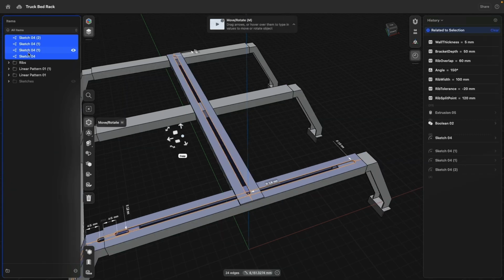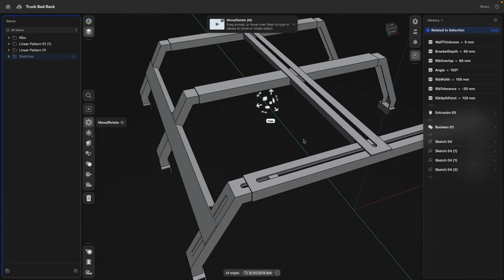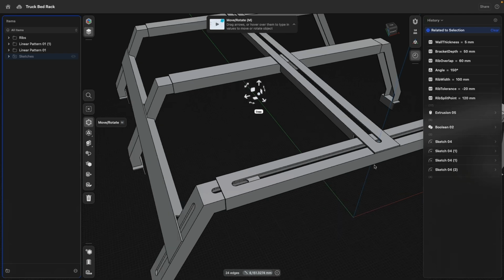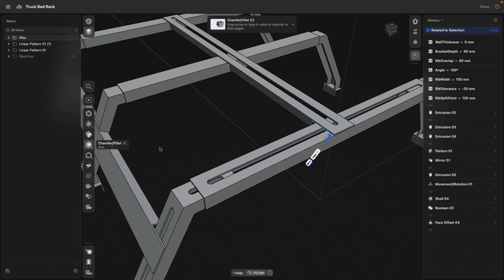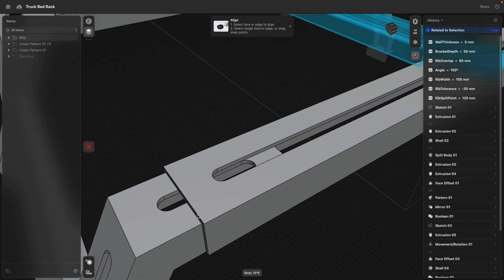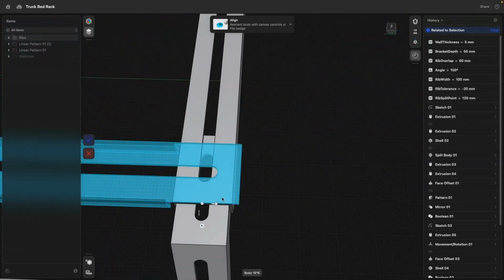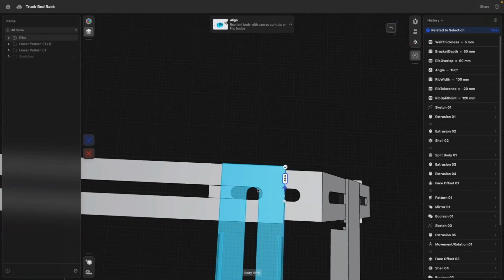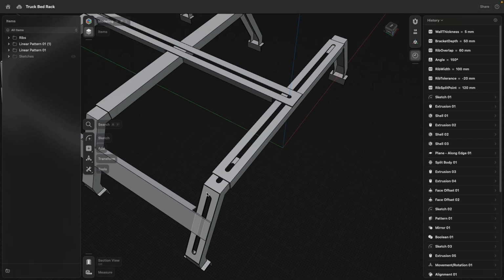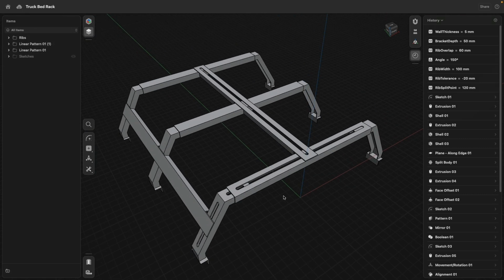If we put all the sketches into this folder, then I could select this edge and say align to this edge, bring this over so it snaps now, so I can see, oh, there's a little bit of an overlap. So on this, for example, the position could be changed. I just exit the sketch because I was just only quickly prototyping how this actually would work.